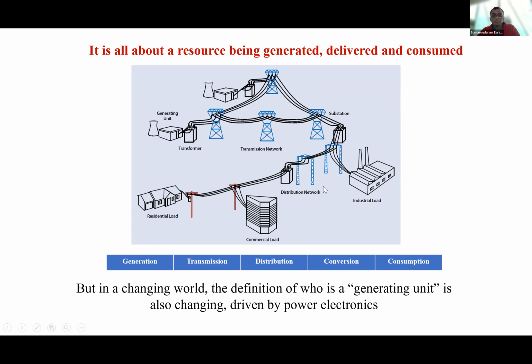Resiliency also increases because if you do have a failure in the transmission system or the distribution system due to whatever reason, it could be weather related, it could just be a catastrophic failure in a certain power station. So if you have, once again, distributed energy resources, solar, battery energy storage, small wind, etc., one could just meet local demands for power from generation that is happening locally, right?